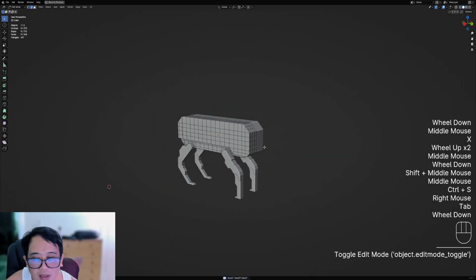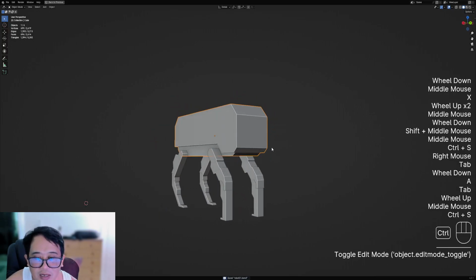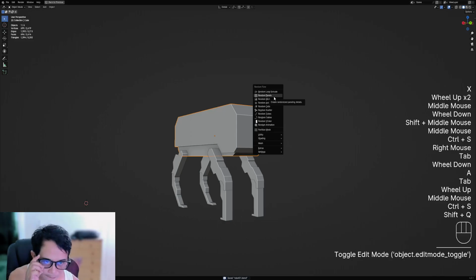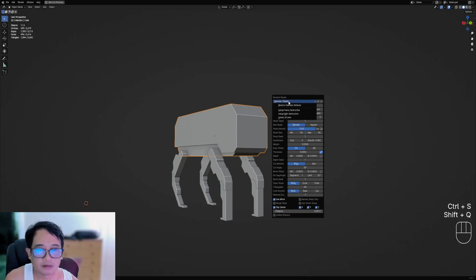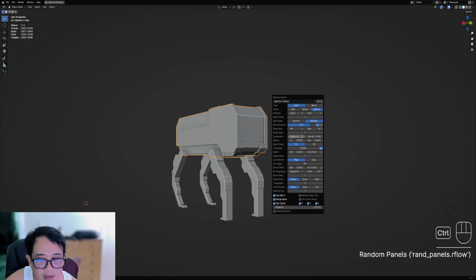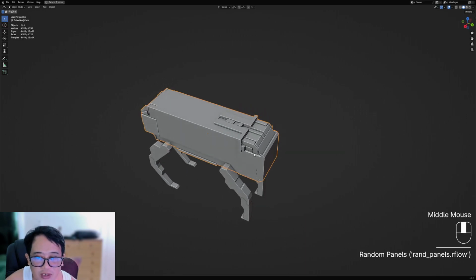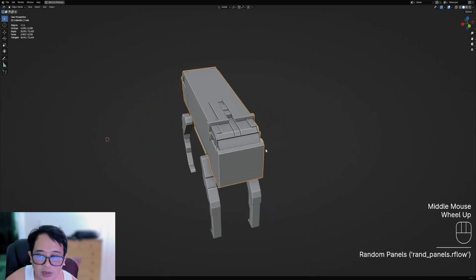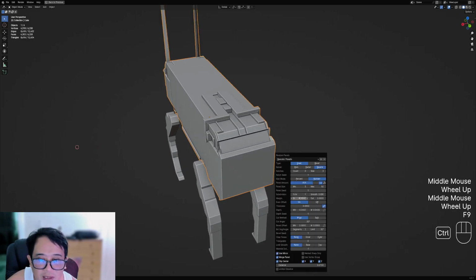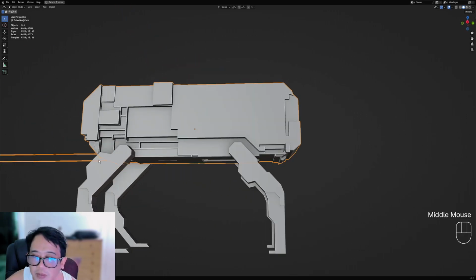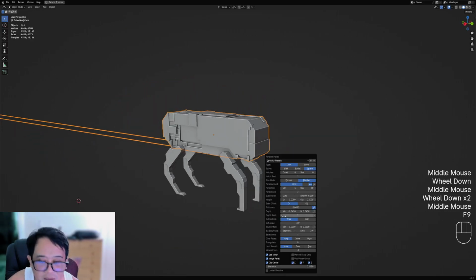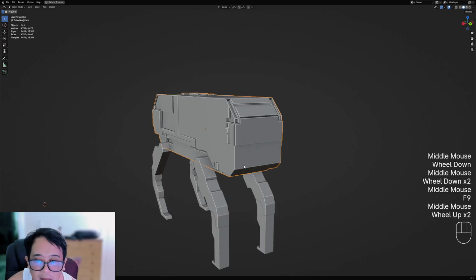Okay, let's try the presets that I made in the previous video. Merge heavy destructive. I'm going to just straight up use it and not use partition mesh. But let's see. Increasing the distance of the split. You can see the spikes, that is based on the sharp angles. You can just use split to get rid of that.